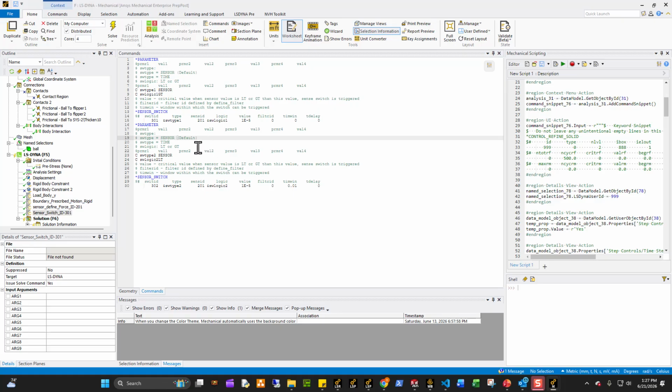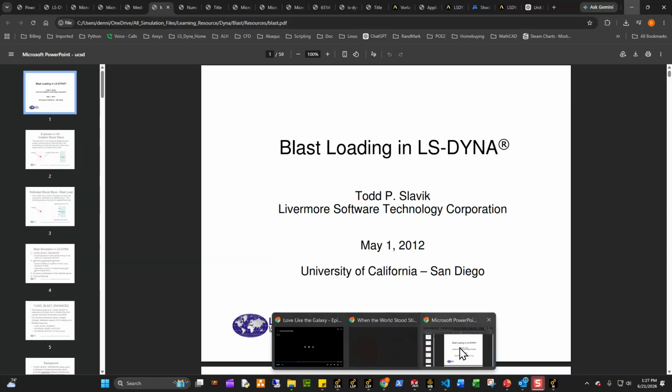And that's going to essentially allow you to flip back and forth between those two switches, which is why I want a delay of 0.01, because this delay of 0.01 is going to allow us to basically turn off the previous sensor and allow the flipper to have enough time to come back. And this is the little trick that we have to do to be able to sort of look at the correct behavior for the flipper, to give it enough time to come back.